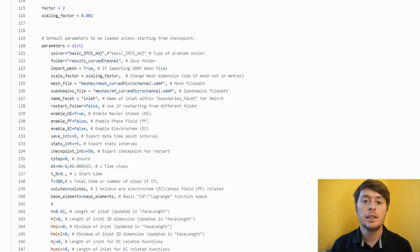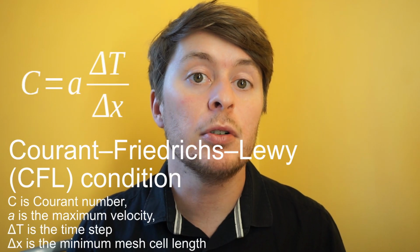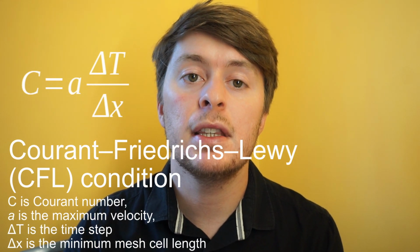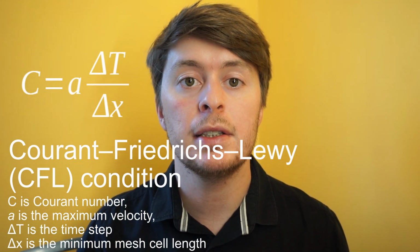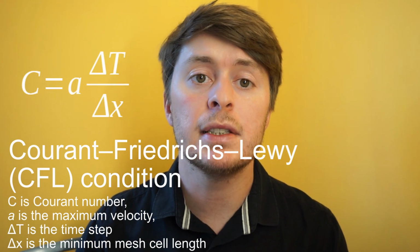The other things we need to consider is the time steps. And in this case, we're implementing the CFL condition, which is the Courant, Friedrichs, Lewy CFL condition. And essentially this will calculate the optimal time step based on our mesh maximum size and the flow rate we're going to be using going into this mesh.